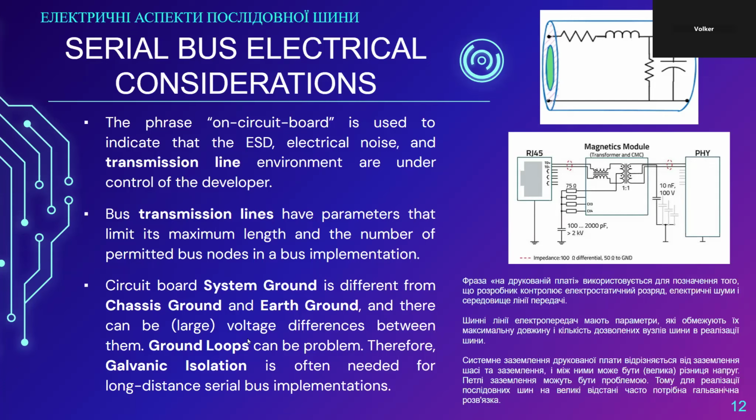And if that is not practical enough, for example, making sure that no electrostatic damage occurs might be as simple as the designer saying that the circuit board needs to have an enclosure. It needs to have a case so that no user can actually touch the circuit board. That might be enough. The electrical noise environment might be enough. It might be enough that there's a good ground plane, that one of the layers on the circuit board is a decent ground plane.